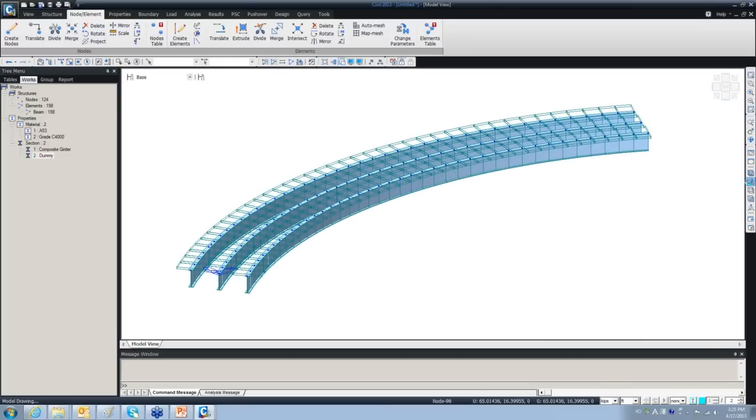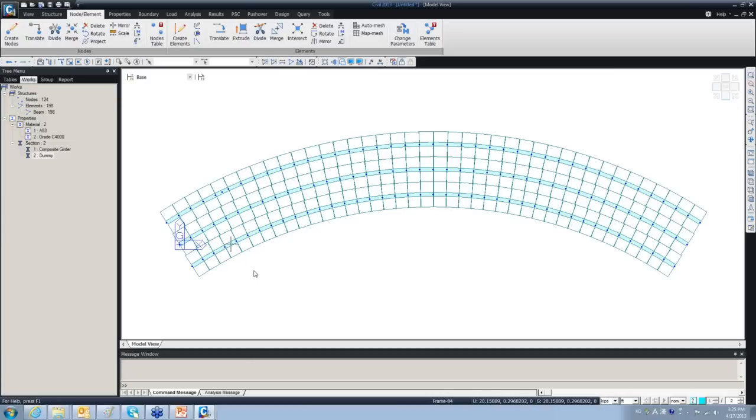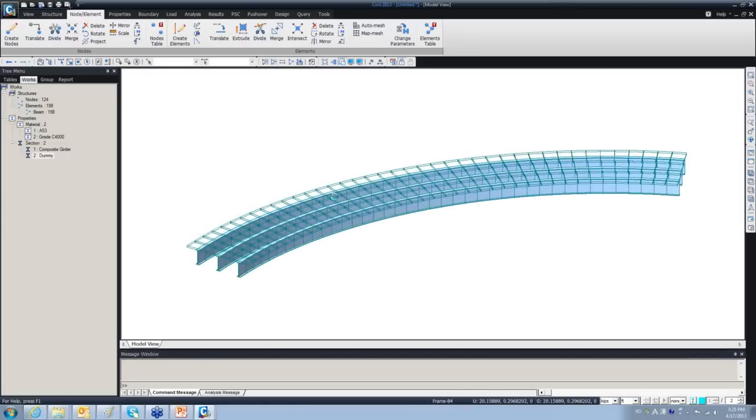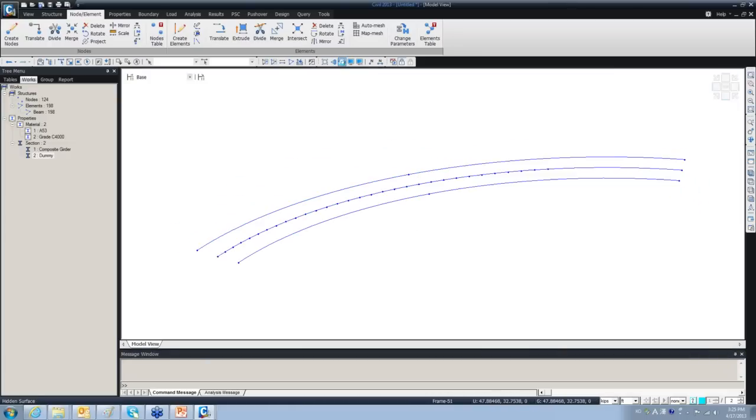All right, if I go to the top view, I want to select a couple of nodes, because see what we have. If I turn this off, in the real model, I have only one-dimensional elements, which means I cannot really create the cross beams unless I define additional nodes in the Z direction, which gives me a third dimension, and then I can define those X braces or cross frames.